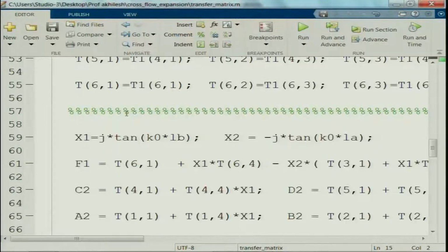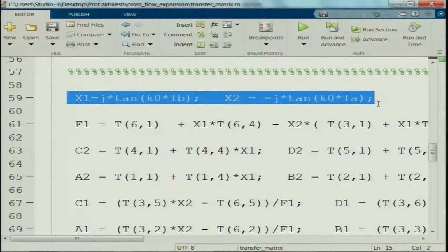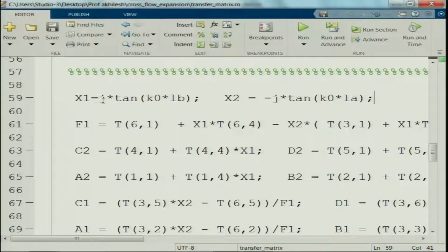Now is the time when you apply your boundary conditions. Like I was saying, these boundary conditions are quite messy; they are not that trivial, just very tedious. We have to define a few variables with a view to finally get a transfer matrix. The detailed derivation you can find in the third chapter of the book on ducts and mufflers by Professor Munjal, but again I am presenting it here. The expressions are given in the book, you can derive them on your own also. Just follow the road map and you will get it.